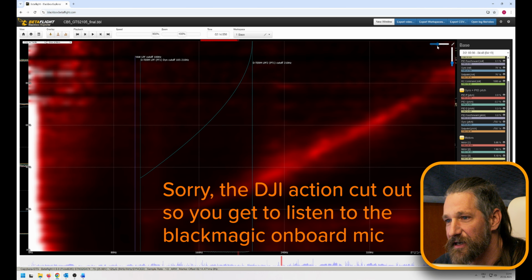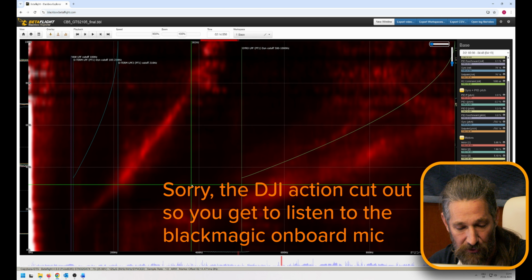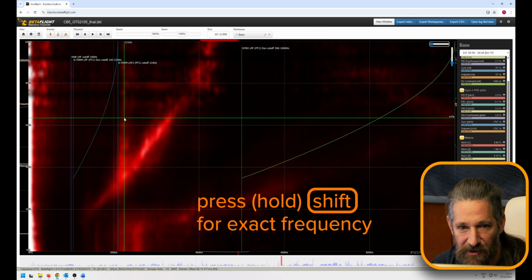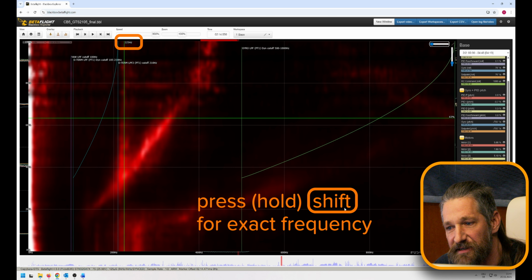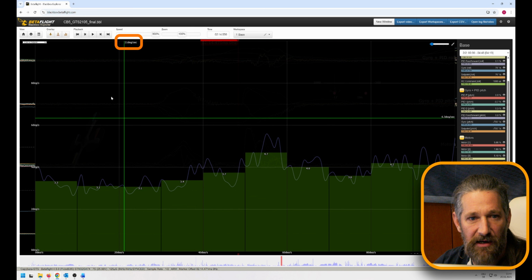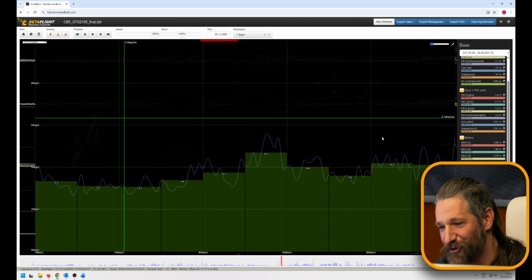Over here you can zoom in on the lower frequency region if you want to single out a harmonic. For instance, this build has one harmonic at 220 just on the pitch axis. And you have error versus setpoint, which tells you how much error depending on setpoint.